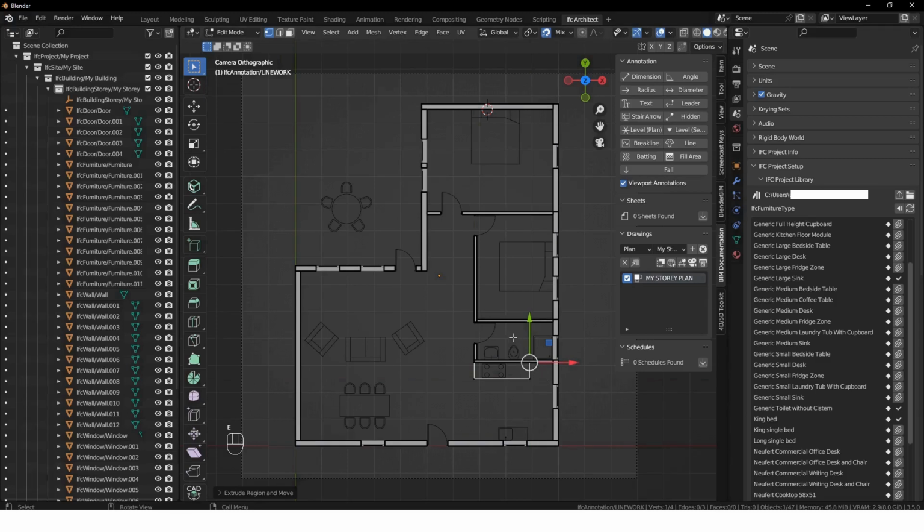E Y, and then we can select 2, which is for the edges, and select that edge, and say Shift D X, and we can say 50, and then we can say E X 800. Then we can select these, say X, and delete only the faces, and then we're left with the outline. Then we can select these as well.